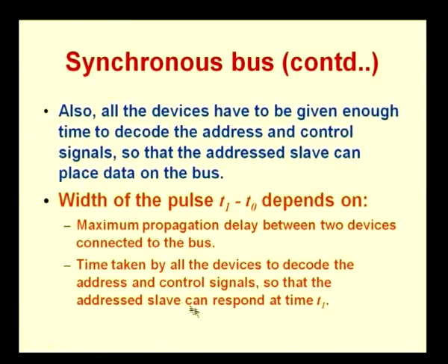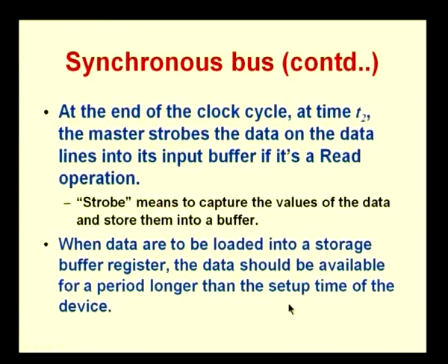Okay, it will have some time that it takes in order to get the data and put it on the bus. So, that setup time also has to be taken into account. So, t1 minus t0, this width of the pulse, is dependent on these two factors. Okay. And at the end of the clock cycle, that is at time t2, we said the master will strobe